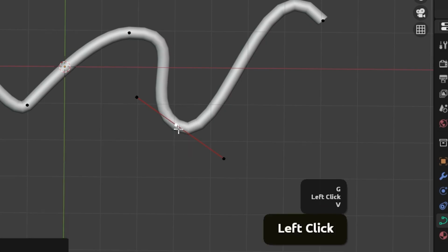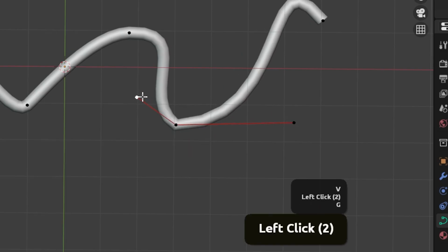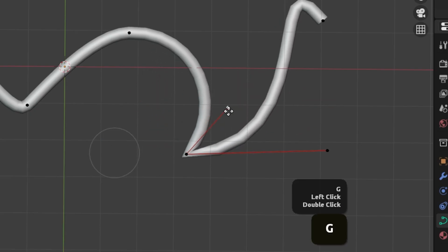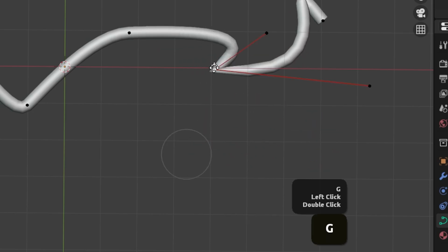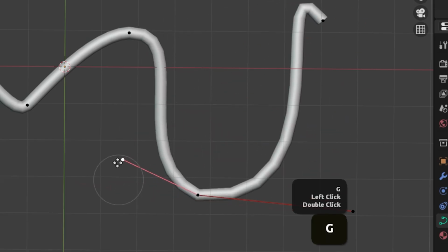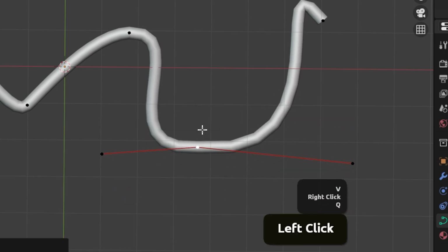Then there is free. If you want sharp or smooth corners and the most bit of control, you should use free, since this allows you to move the handles independently of each other, and they won't change their placement when you move the curve. Toggle free align lets you switch quickly between free and aligned.